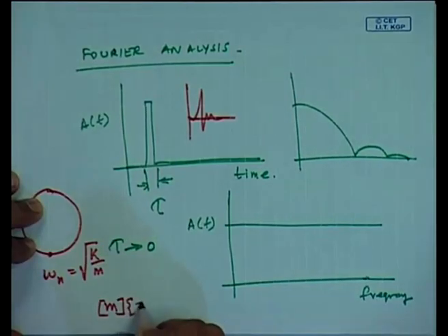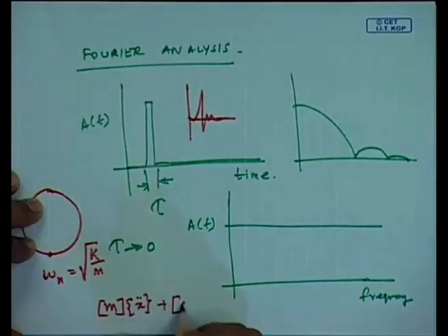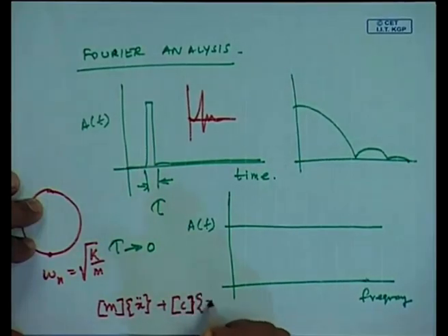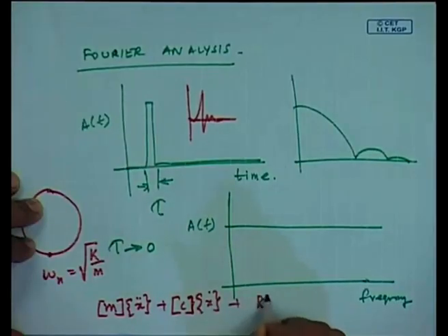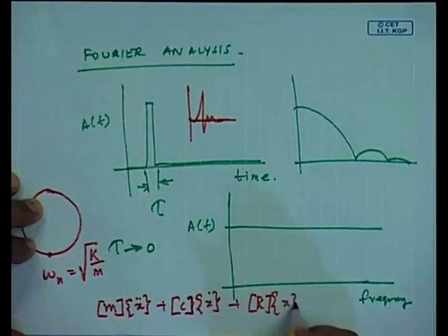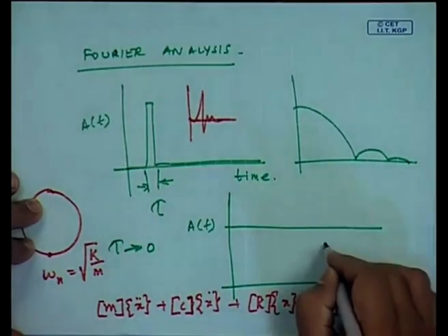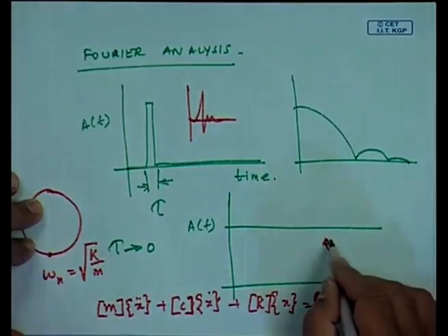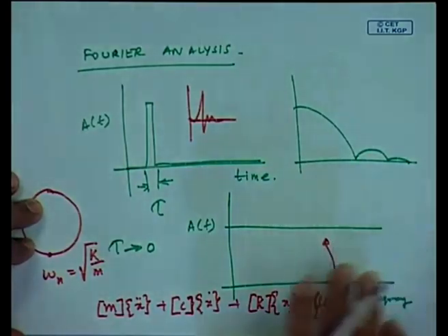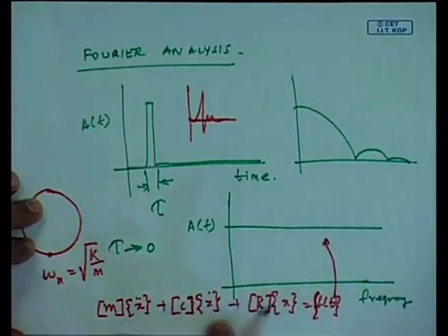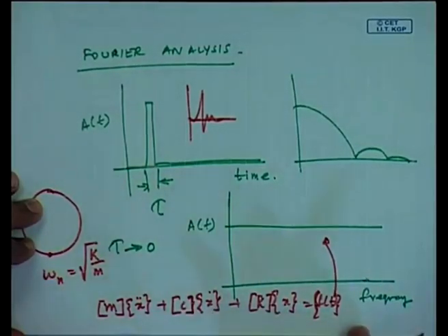If I were to pose the problem another way, suppose I can model the bearing by this set of equations, with a forcing vector on the right hand side. So, this force is actually this in the time domain, but in the frequency domain this would look like this. That means what? The system, in this case the bearing, has got excited at all the frequencies and it has got excited at its resonant frequencies.